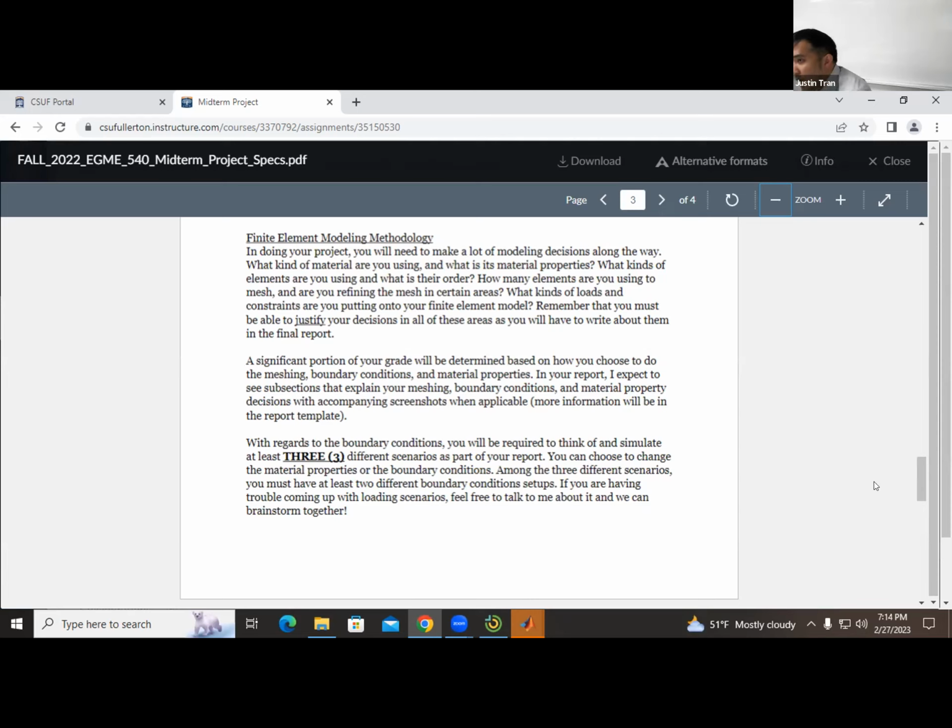In this class we have a very hard limit because we're not using the commercial version of ANSYS. After a certain point, ANSYS will say no more elements, you have to buy the full software. But in reality there are limits too: if you run a mesh with, say, 40 million elements, it could take a couple of days to finish. A lot of times you don't have that kind of time because you have deadlines.